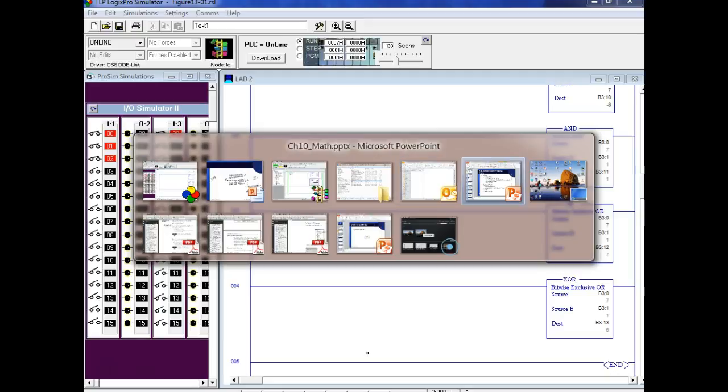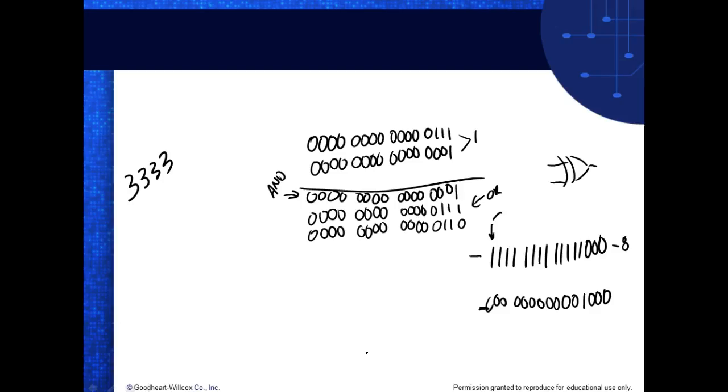So let's say I've got a 16-bit. I'm bringing in a 16-bit input, and you can understand. So now what I can do, instead of playing around with my inputs, instead of bringing in one little bit at a time, right? You understand? What can I do? Well, I can load an entire 16-bit input port at one time. And then I need to start figuring out what's going on with those bits. I can treat them as a number. I can treat them as an integer, right? You understand that? So what we're doing here is actually kind of treating these like numbers.